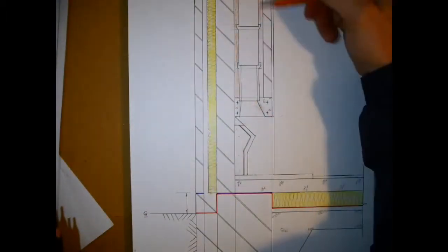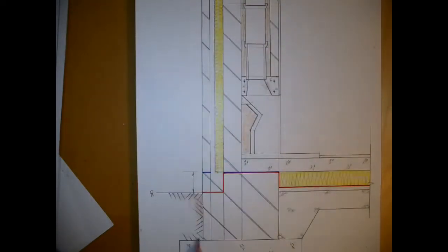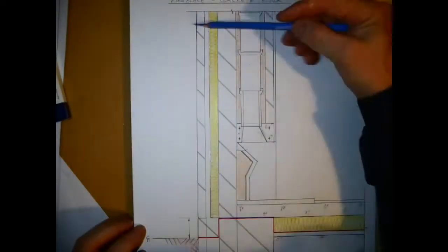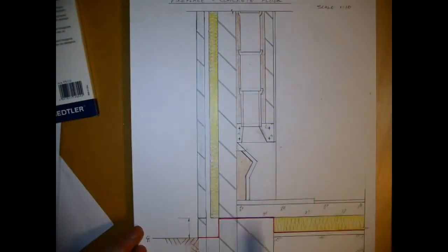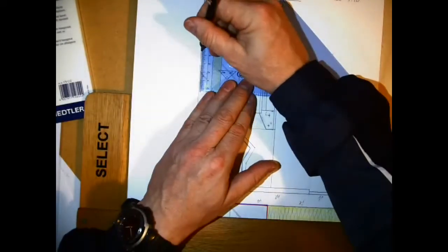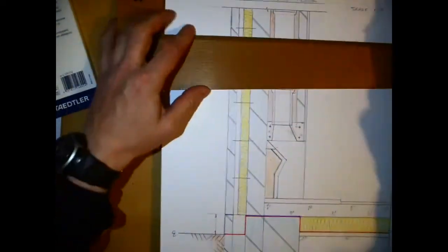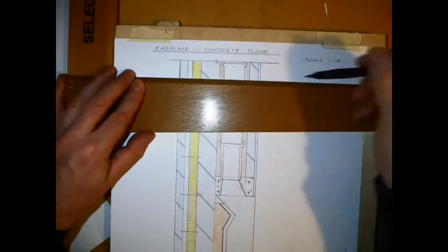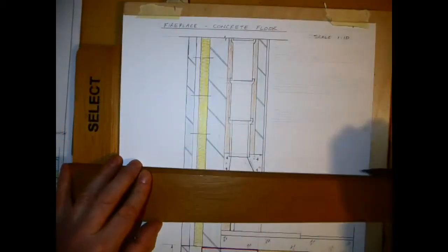And the fill, I'm just going to use a different colour for the fill, the 1 cement, 1 lime, 12 sand, and it will be put in behind the fire back. The fire back, when it's put into place, behind that, it's packed in layers, and then the top, the shelf, is actually finished off normally with a fire cement, and a fire is lit. There's cardboard on the back of the fire back, so that it allows for expansion and contraction as well when it's in use afterwards.